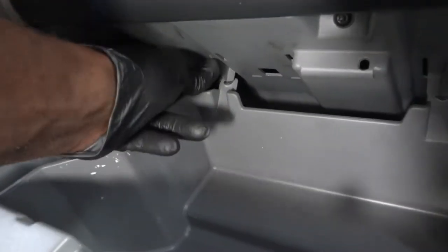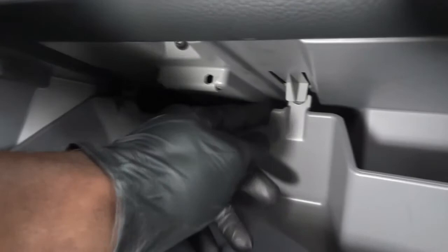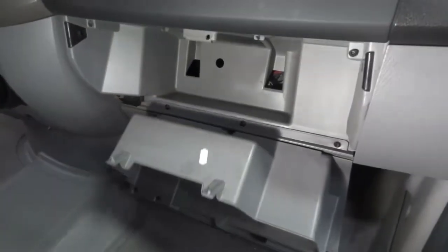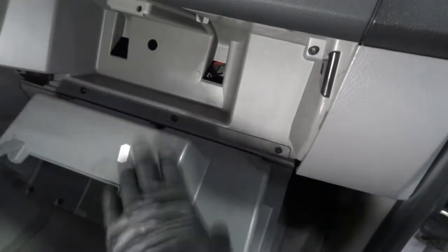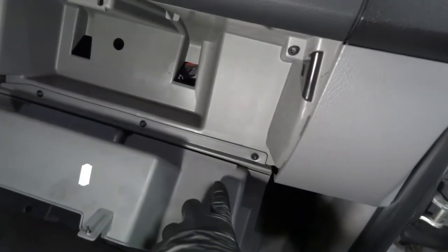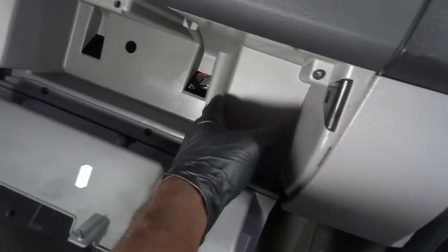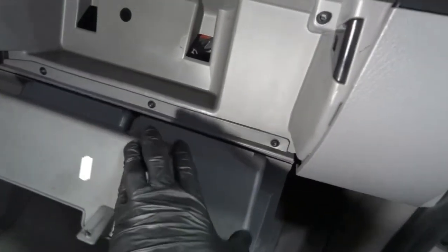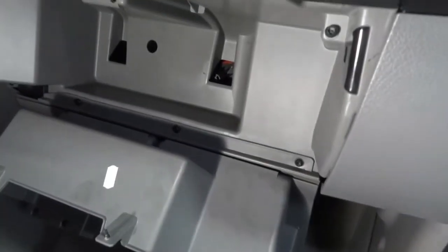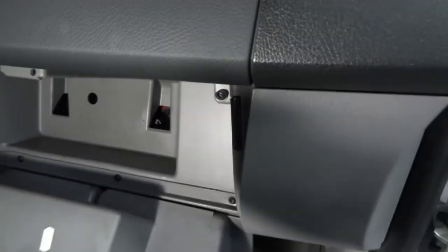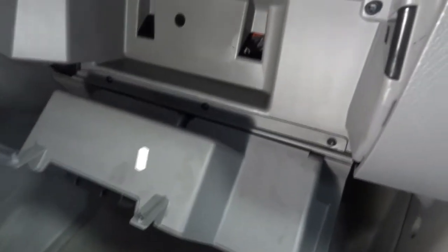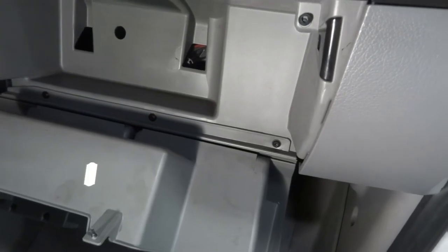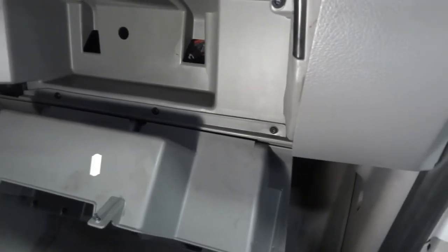Right there. So what you're doing is just push this up, okay, and then same thing on this one, push this up, and then the whole glove box is gonna swing down. All right, so the glove box, this plastic glove box here, is bolted to this plastic frame, and it's got 3 little tiny torque bolts, and these torque bolts are T25 bolts. So we are going to undo these 3 T25 torque bolts.